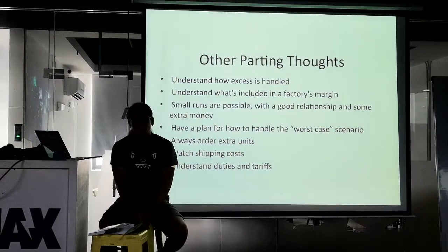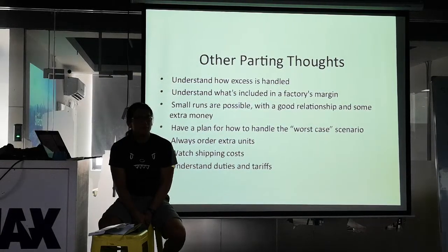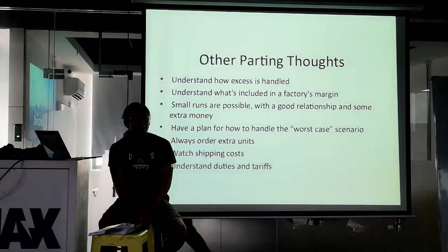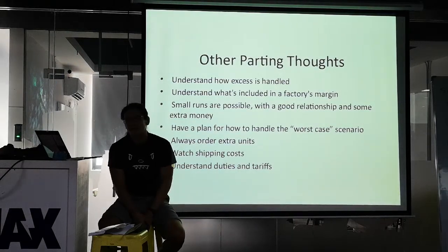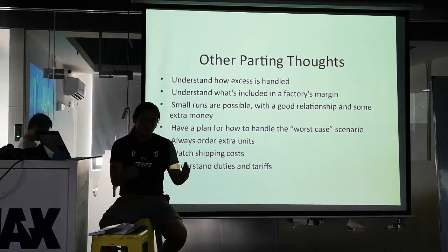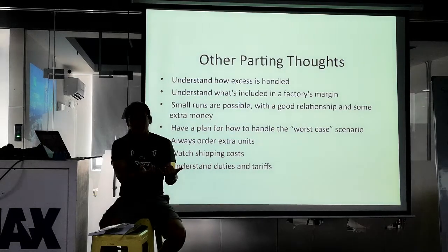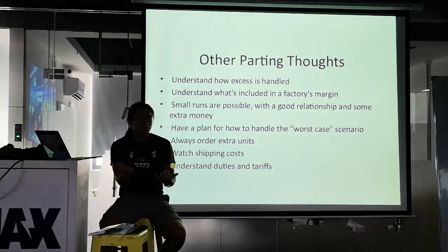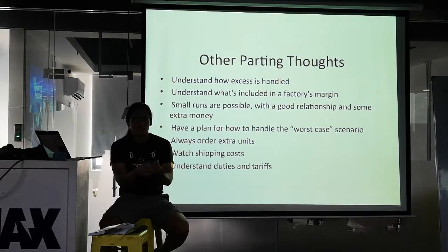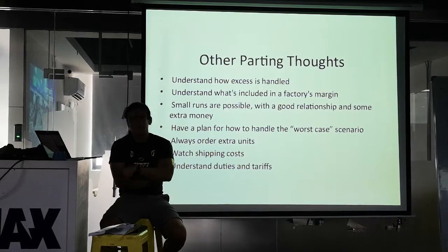If you're planning to do a user test study and you need 100 units, consider building 120 or 150 of them because some of them aren't going to work. Some are going to get broken. There's a whole bunch of things. So order a few extra units beyond what you absolutely strictly need. Because if you needed 100 units and one of them is broken and you have 99, you can't just go back to the factory and say, hey, can you fire up that whole line to build one? Right? They'll want you to build another 100 units for that one missing one. So it's much easier to throw an extra one in at the beginning, build a few extra, versus asking the factory to go ahead and build a bunch later on.